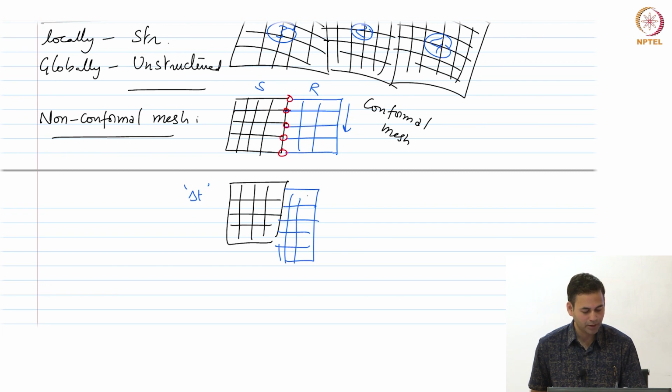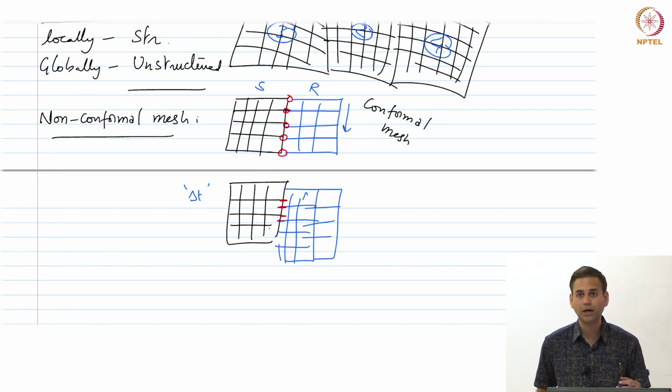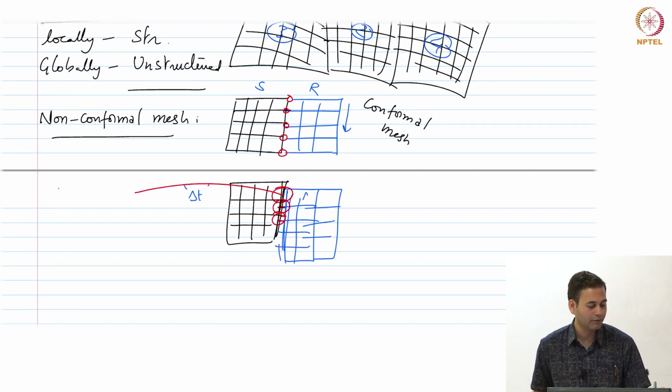This is the same rotor I have drawn. Okay. So, it has moved to a different location. Now, you can see that the nodes are not matching, right, they are all non-conforming. As a result, we have to introduce extra effort to deal with the flux transfer between these faces, okay, because we know that this particular face here is transferring the flux to this particular face here, but we need some special treatment to handle these extra non-overlapping zones. Okay.